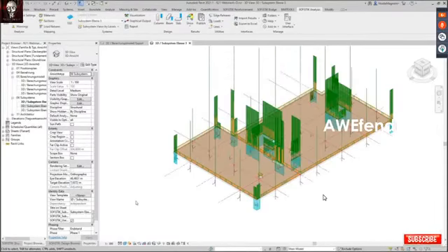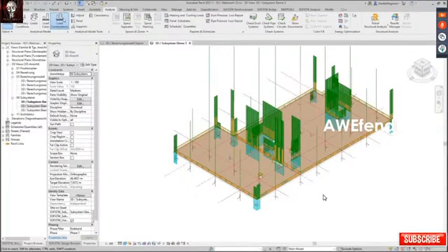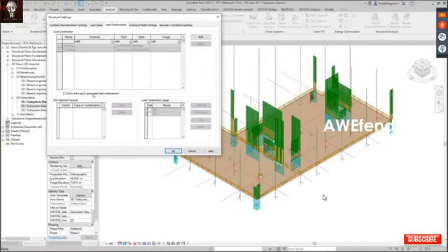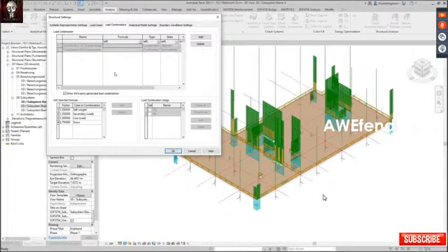These load combinations are now created and saved inside of Revit. This means if you know already the load combination dialog of Revit, they are also present there as a third-party generated load combination, are visible and are, let's say, equivalent to the one generated with this dialog. It's just from our point of view, more comfortable and more complete to do them with the SOFiSTiK dialog.